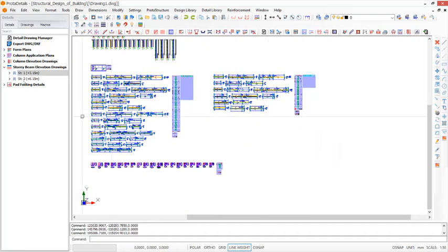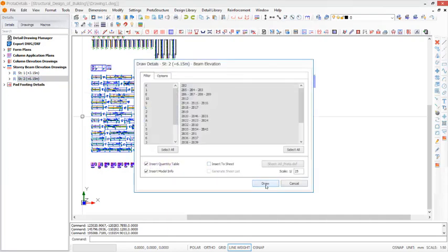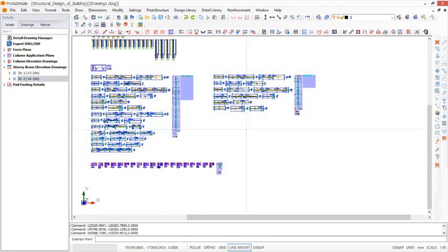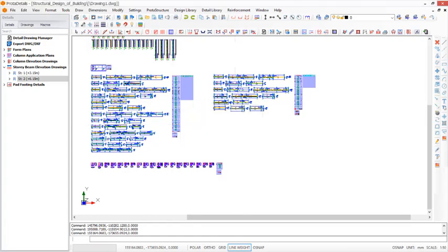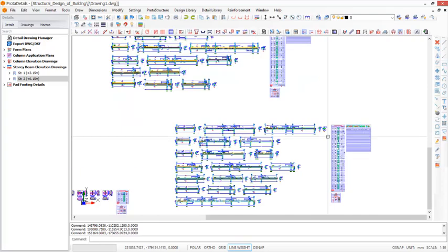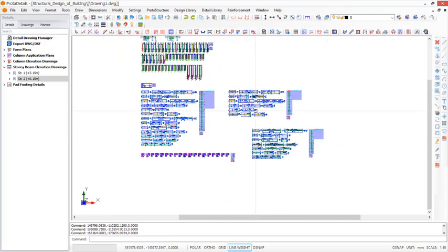The same thing we'll do for the roof beam, so you have to draw that. Click on draw right here. So you pick these provisions to have the detailed designed drawings of the beams at the roof level of this structure, with the bar bending schedule being generated successfully, just like this, okay.